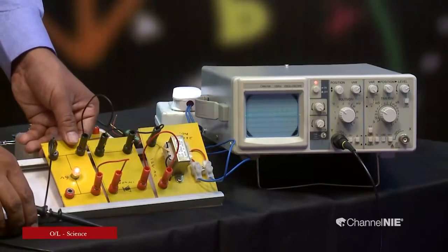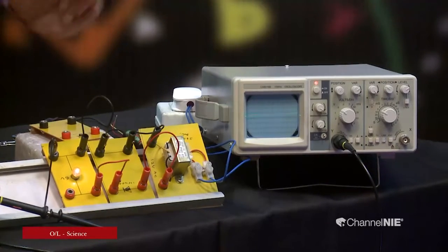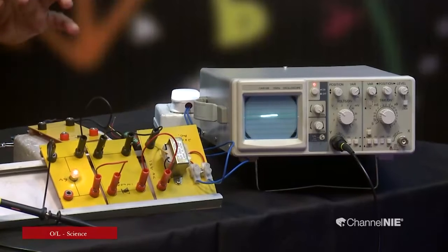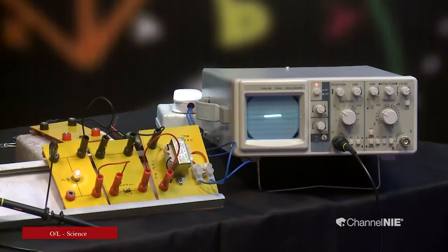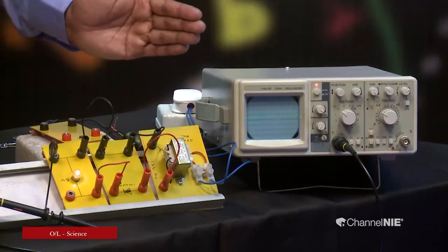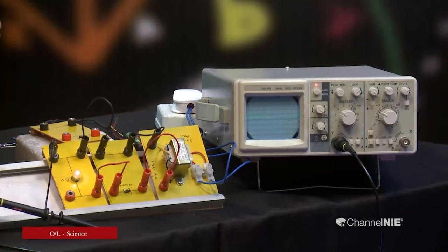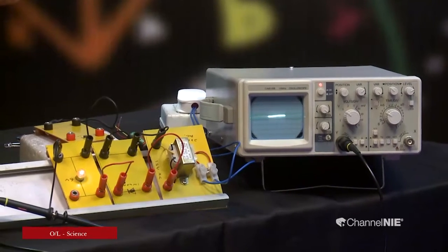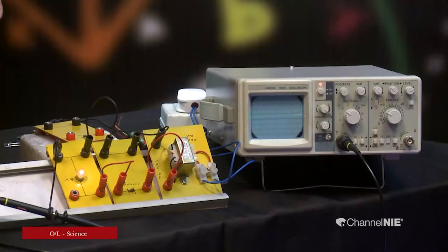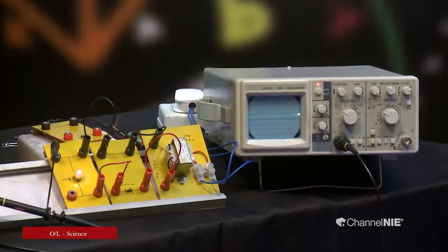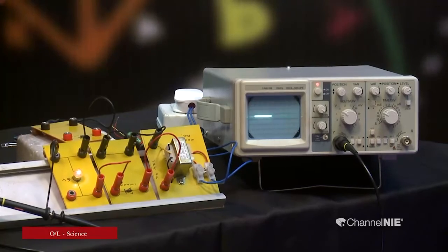Now here you can see that when connecting the diode, the brightness of the bulb also reduces. Why is that? In the previous instance, more current passes through the circuit, but when connecting the diode, only 1/2 of the AC current passes through the diode. That means the power of the electricity has been reduced.